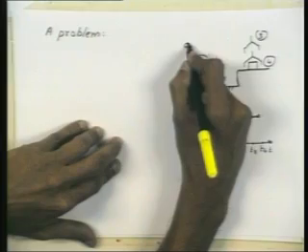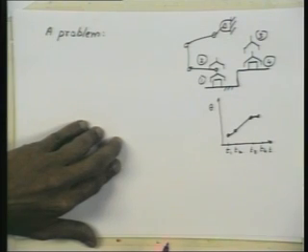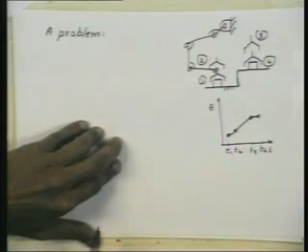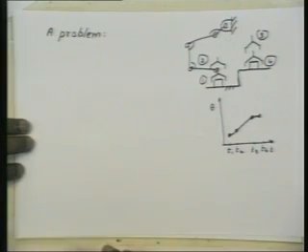So if I draw it at some position, imagine that this is the robot. Fine. How do you calculate these joint angles? This particular problem is called the inverse position calculation problem in robotics. So given the end effector position, determine the values of the joint angles, or it may be a prismatic joint, in which case the extension of the joint, such that the gripper is placed at the position you specify, right?